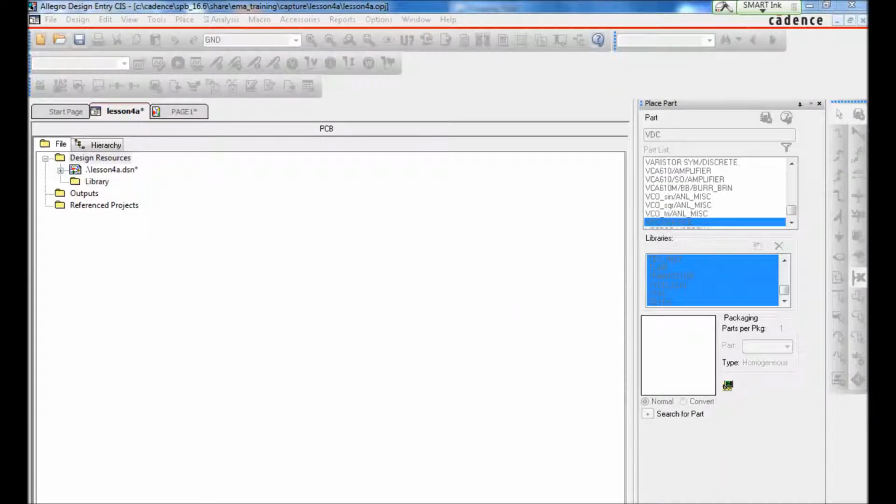Eddie here. We're going to start off lab 4-2, creating a schematic page. So the lab objectives here are viewing a reference schematic, add a header connector, mirror the connector, add and copy decoupling capacitors, add wires, add net aliases, add no connect and power ground symbols, add bus entries and wires, add off pages connectors, and view the design cache.